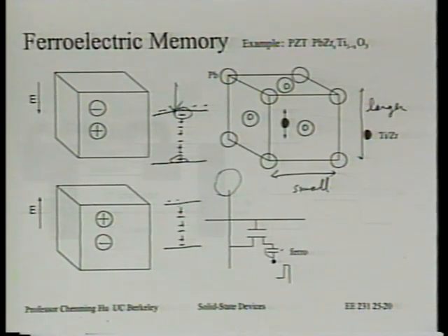And then the remaining question is, how do you store it in a non-volatile manner? Well, you have to be given a signal. Perhaps the PC pushes a signal saying save, or the circuit detects the voltage dropping. So using the last 1 millisecond left to store everything, you can do that just by applying a particular voltage. You can save that information.